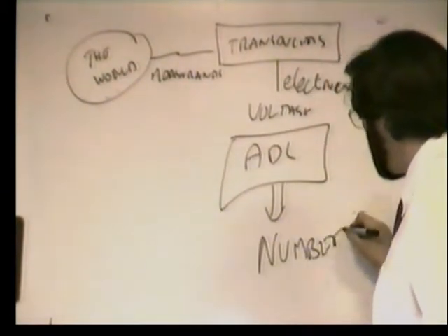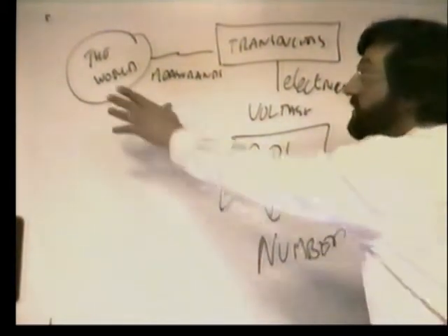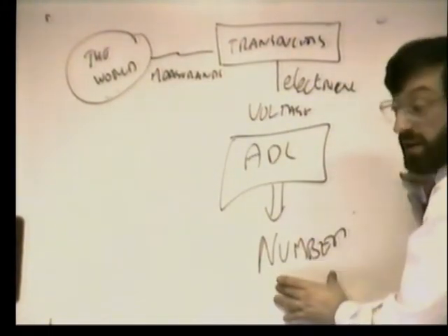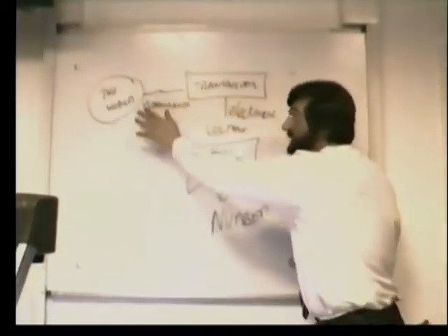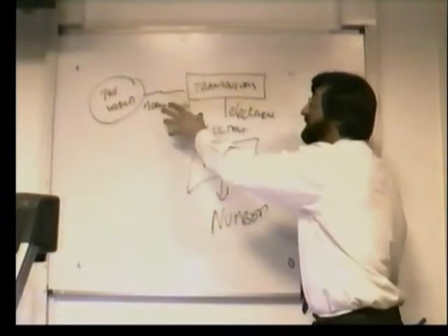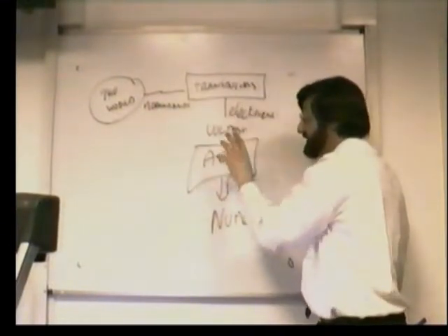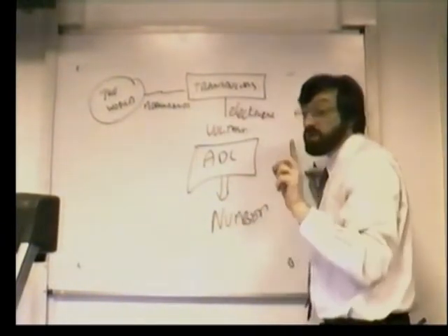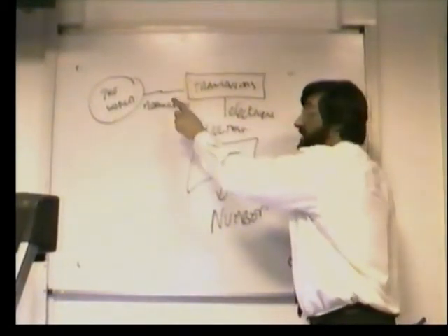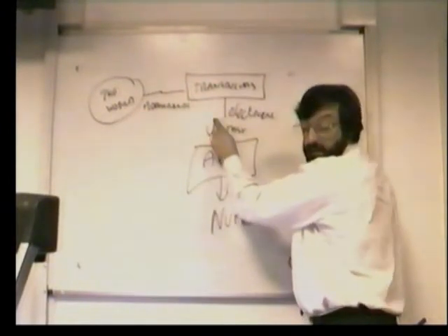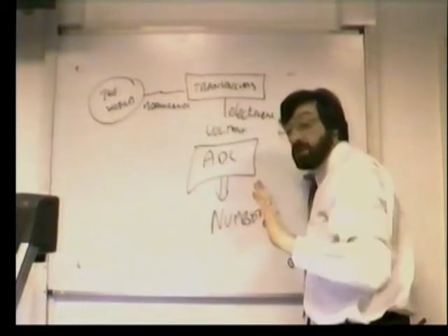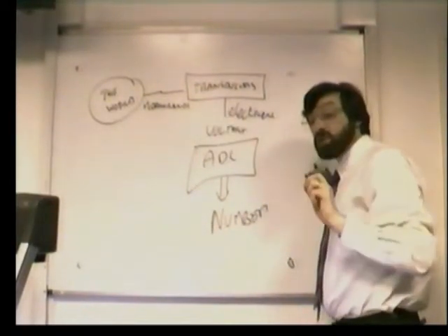And at last, our computer can do something, and it has, through this whole chain of devices, extracted some knowledge and information about the outside world. It now knows what's going on using these devices, transducers, ADCs, and that's giving us numbers. And what's the rule? There must be a known mathematical relationship between the input measurand and the output measurand.